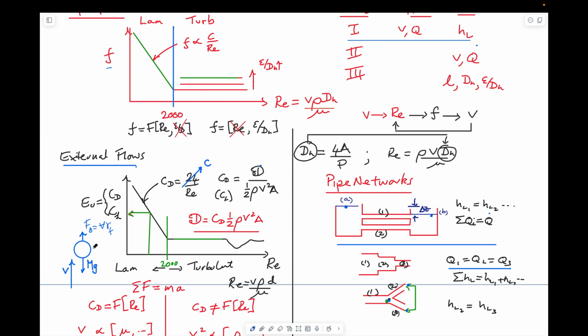If it's air, this might be very small. If it's a liquid, it might be larger. Again, the Moody-like charts have a portion which, if it's laminar, below about a Reynolds number of 2000, is a function, the drag coefficient or lift coefficient is a function of Reynolds number, and if it's turbulent, then it's independent of Reynolds number. The coefficient of drag is defined, or lift is defined as a drag force divided by a half rho